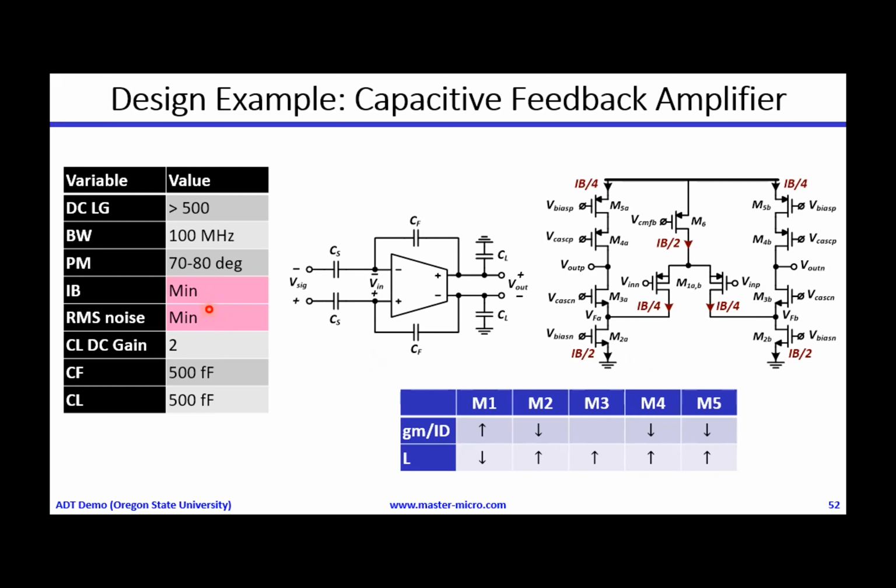So if I go to an expert designer, even someone who has designed this circuit several times before, and ask him to analyze this circuit, the analysis is quite tough. We can actually spend a whole lecture analyzing this circuit. And after we analyze it, we will end up with some complicated expressions that will give you zero intuition, because all the design parameters are entangled together and interdependent. So it would be very difficult for you as a designer to get your specs right. You will have to do lots of trial and error to get the minimum current and the minimum noise.